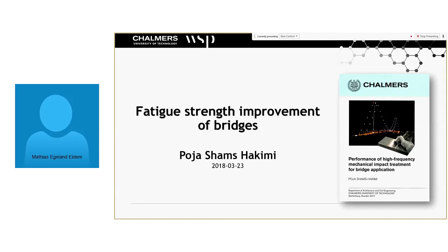Okay, I see. Also, this is only a saving that applies to the top flange of the bridge girder. The bottom flange will not be subjected to fatigue in the same way, because the traffic is on the top side. So this estimate was: I take the total weight and divide it by half. So half of the bridge girder is subjected to traffic, and as indicated, maybe 17 to 20% savings.